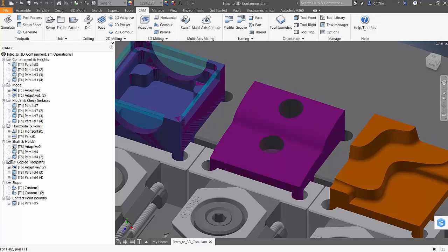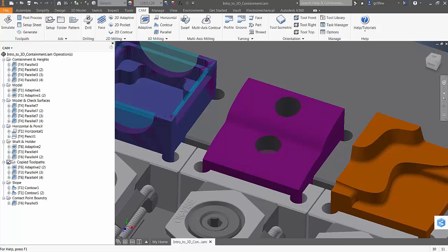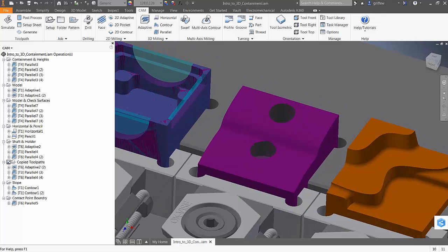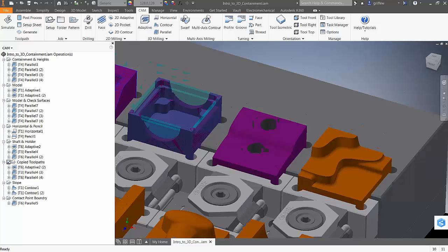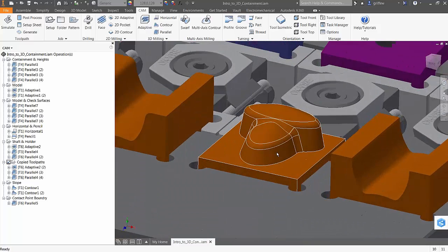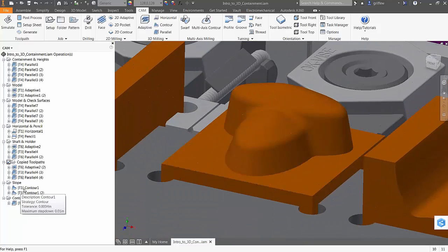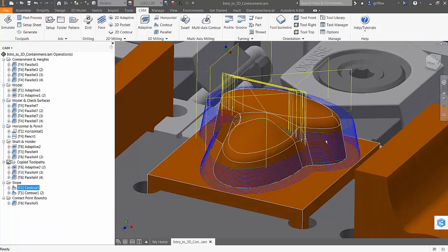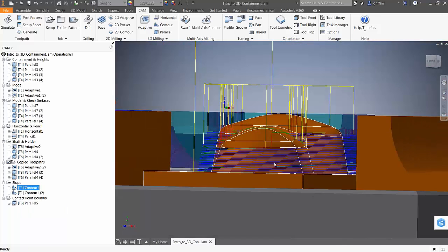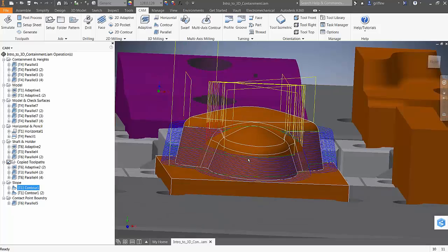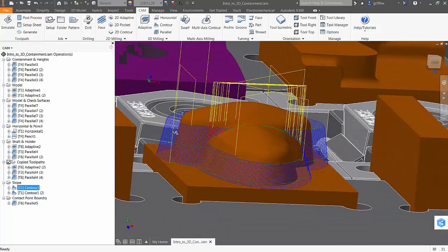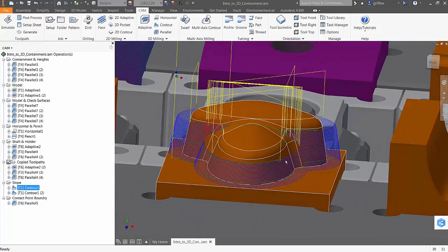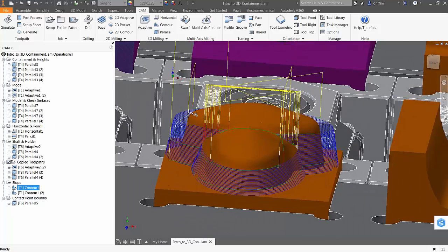Okay, got another question going there. Okay, it looks like Ben is asking. No worries, Neil. So Ben is asking a question, what's the difference between ramp and a contour? So a contour, what it does when you're working with a contour, it'll go around the model but stay at one level. In other words, it'll go around in your Z and then step down, come back into the part and go into the Z.